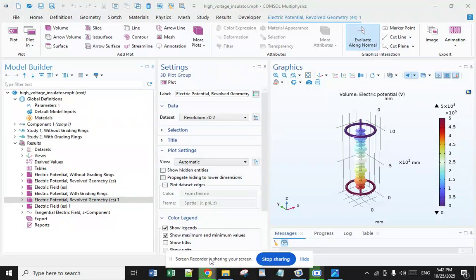The next one is silicone insulators. Silicone or polymer insulators are another type of low voltage insulators. These consist of a silicone body attached to a metal base. The advantage of silicone insulators is their high resistance to ultraviolet rays and aging due to sun exposure and weather conditions. They are also very lightweight and have high mechanical strength.